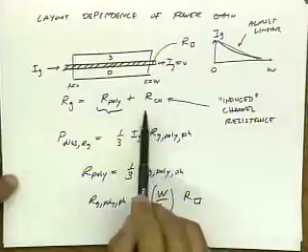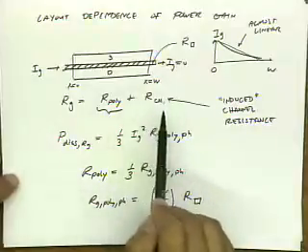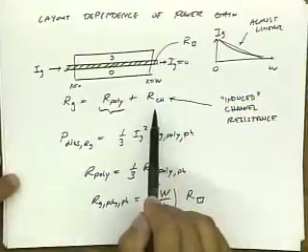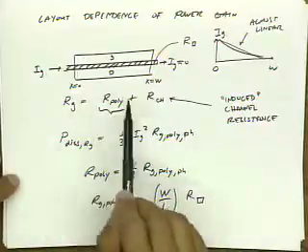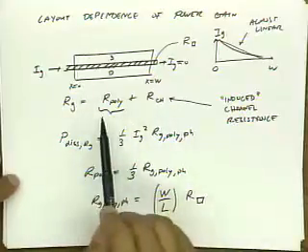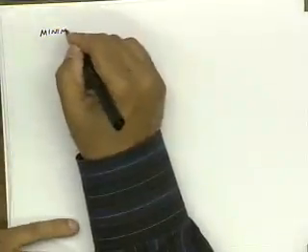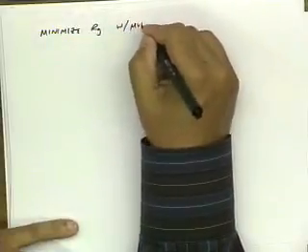So because this term is bias dependent, I can always bias my device to have a higher and higher current and lower channel resistance. And so I can eventually be dominated by just this term here. And this term, of course, does not depend on bias. So one way to minimize our gate resistance is to use a multi-finger layout.